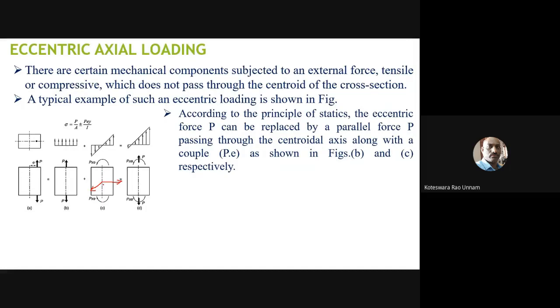So now, if the moment is acting about this axis, either about this axis or about this axis, we'll call it a bending moment. If the moment is acting about this axis itself, this longitudinal axis, we'll call it a twisting moment. So now if you consider the case here, the moment is acting about this axis. If I draw the axis like this, then only I can say this is the direction. Therefore, it is not the longitudinal axis, we need to take it as a bending moment. We already saw how to compute the stress due to bending moment.